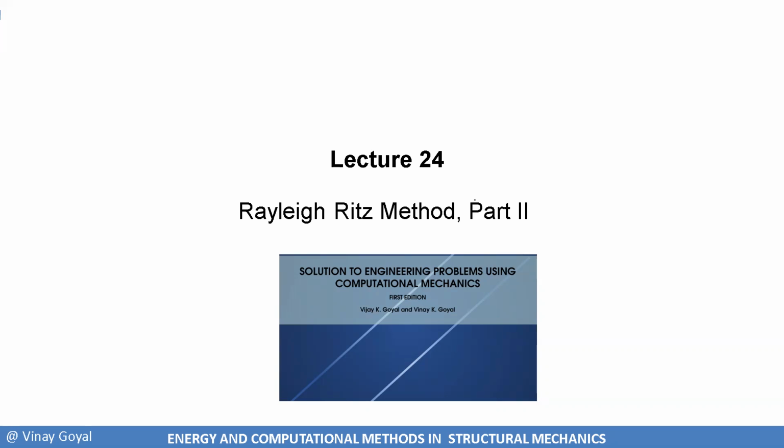So that's one aspect of applying calculus of variations: when you use the principle of virtual work and you make some modeling simplifications, maybe from 3D to 1D or 2D, you will expect some error there. And that's why calculus of variations is so powerful, because it's going to do its best to give you the best Euler-Lagrange equations possible for the given problem. Note that there will be errors in these solutions. These solutions are not perfect, but they're good enough for engineering.